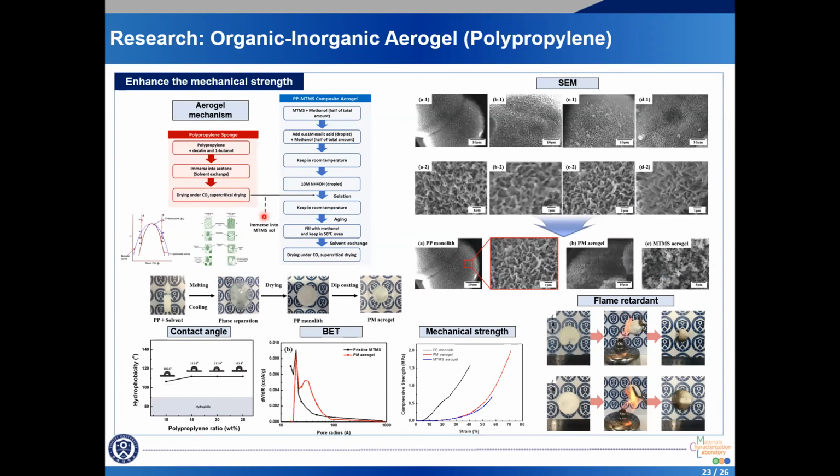In this study, the silica aerogel was formed onto a polypropylene scaffold using a two-step sol-gel process. A great enhancement of the mechanical properties of the polypropylene silica aerogel nanocomposite was obtained. This novel approach of incorporating silica aerogel onto polypropylene shows great potential as a durable, superhydrophobic, and corrosion-resistant thermo-insulating material.